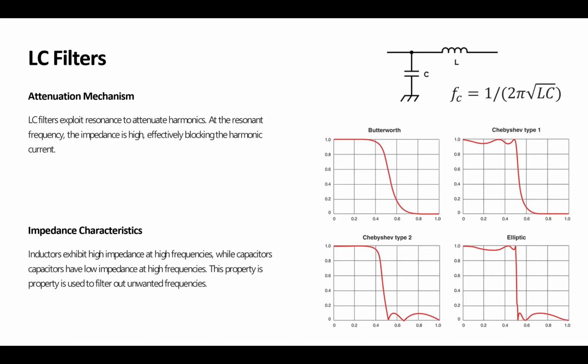If you want to come up with one equation to describe all of them, you can't have both integral and differential in the same equation. So you have to differentiate once more to have only differentials, meaning now you have a second order differential for the inductance and a simple equation for the capacitance. Makes sense? This is why we call this a second order filter: the equation that models the behavior of an LC filter is a second order differential equation.